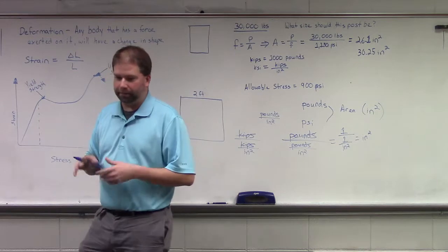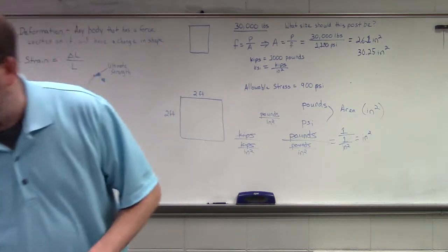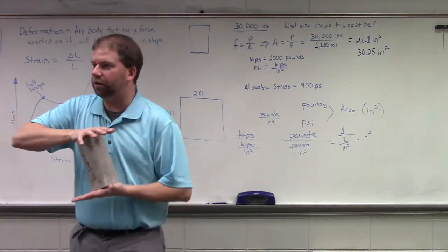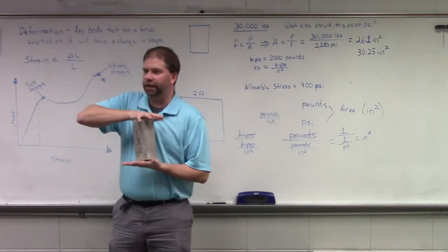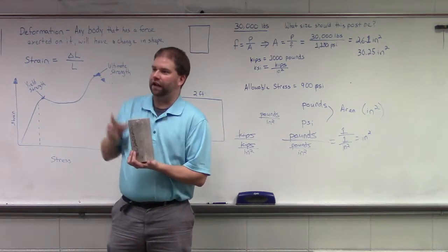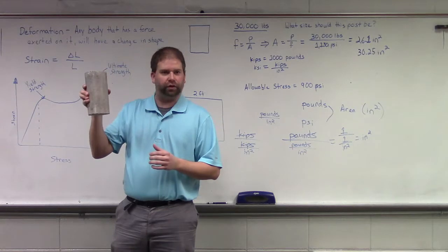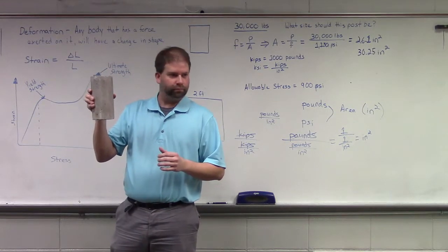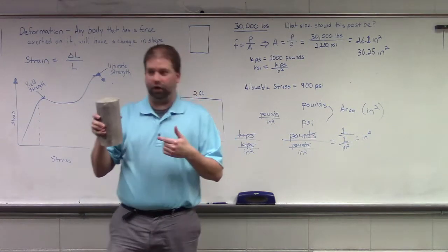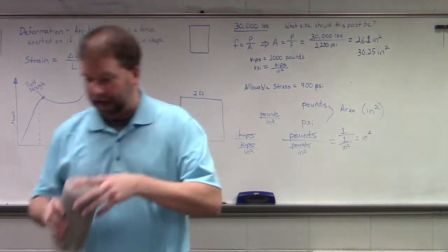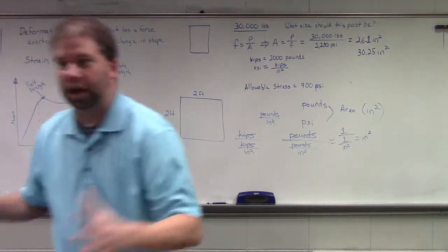The reason being, if I compress on this concrete, but the compression that I do is in that elastic limit, when I take the load off, it goes right back to its initial shape. We like that in our constructed world, right? We like things to stay, generally speaking, in the shape that we make them in.